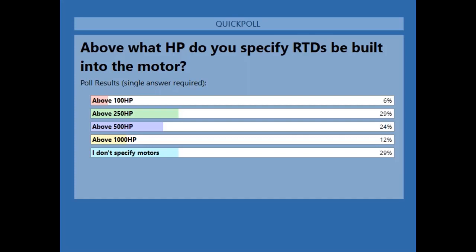Okay, another question came in. Is the most common practice to use 6 RTDs and use the other 3 as spares to swap? Kevin, I think y'all are only putting 6 RTDs. I don't think you've got 9 in the stator. If you do, that's actually a good idea. So you'd have 3 per phase, and if one of them goes out, you could use the third one. The problem with RTDs when they bring the wires back is you never are really sure what phase an RTD is connected to, because there's just a bunch of wires brought out of the terminal block.